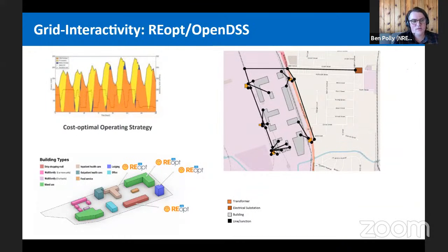So say there's a community with a high level of renewable energy integration. There might be some times where a lot of energy is being exported back to the grid. You could look at how that impacts the voltages at different points in the grid, and whether those voltages stay within the required limits, or whether additional controls are needed to handle that. Next slide.